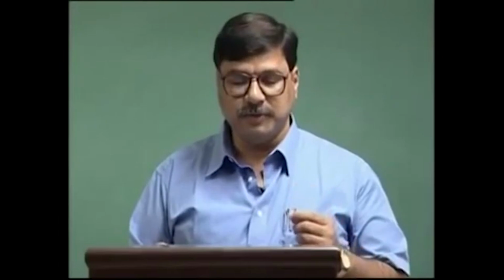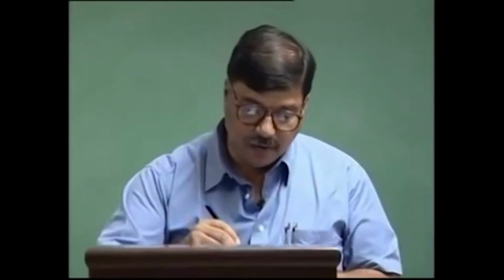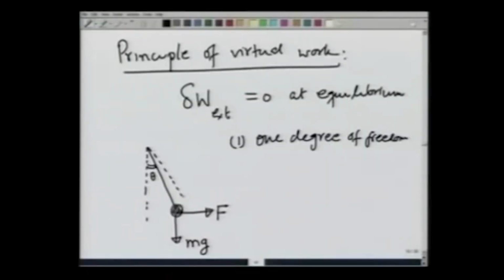So, I can make a virtual displacement changing that theta only here. The principle says that delta W of only external forces is equal to 0. The only external forces that are working on the system are F and mg, with T being the constraint force, which does 0 work. So, this is only external. Let us make a virtual displacement of delta theta.